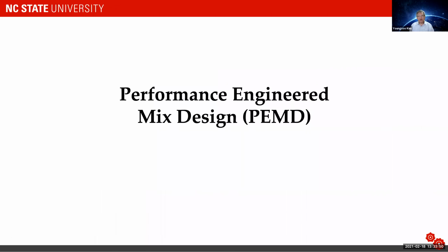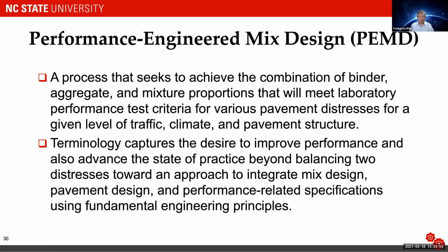So how do we use this information in PEMD, Performance Engineered Mix Design? PEMD is simply a process to get the optimal combination of aggregate and asphalt binder for the given level of traffic, climate, and pavement structure. But this terminology, PEMD, captures the desire to improve performance and advance the state of practice beyond balancing two distresses toward an approach to integrate mix design, pavement design, and performance-related specifications using fundamental engineering principles.